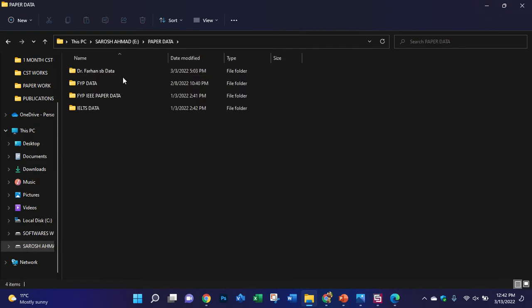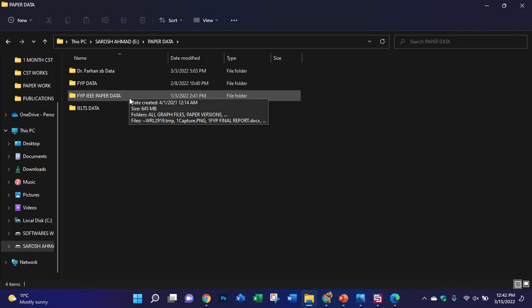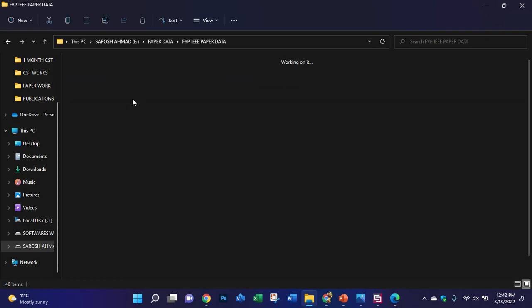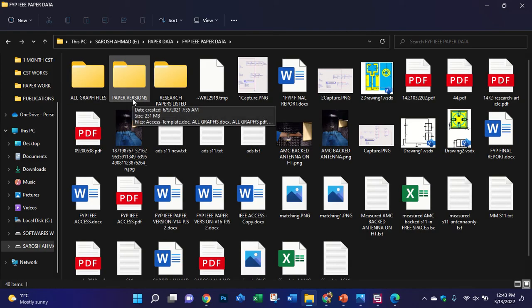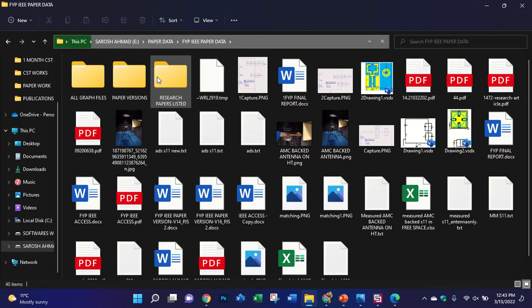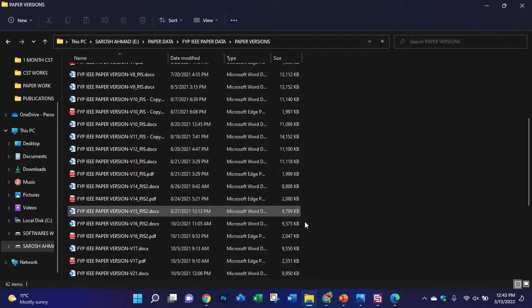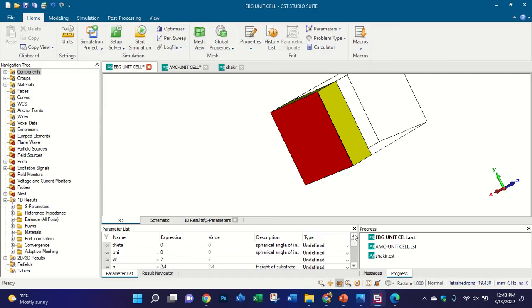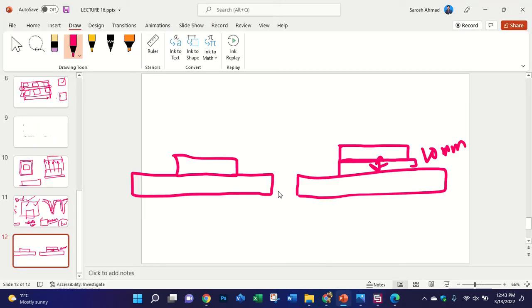How to get the distance between the antenna and the metamaterial? There is no formula, you just simulate. You simulate multiple times, like what happens with 0 millimeter, 5 millimeter and 10 millimeter. What is the distance limit? If you increase the distance, your antenna profile will not be very thin, it will become very thick.